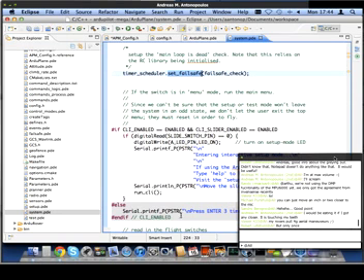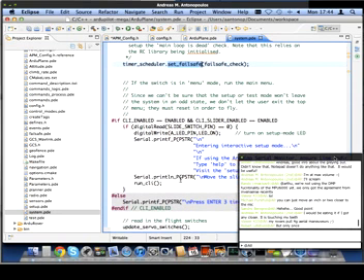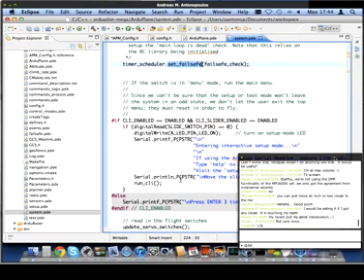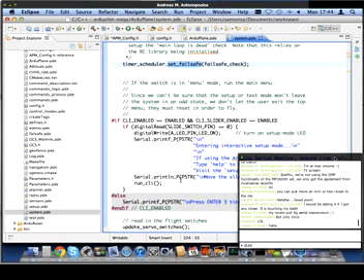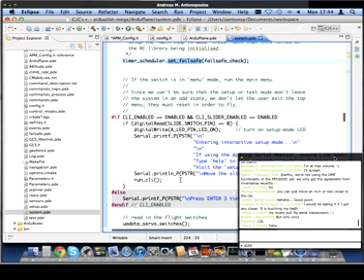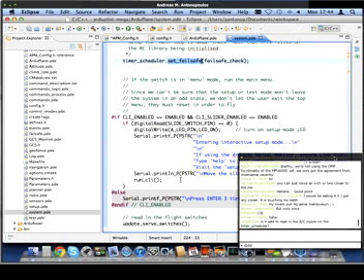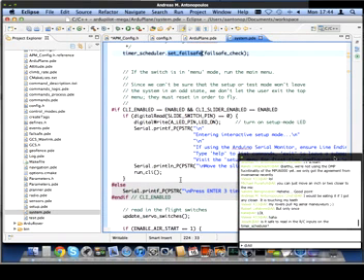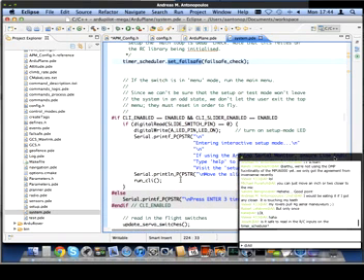It also provides the heartbeat behind things like the analog to digital converter, reading the gyros, reading the accelerometers, reading the MPU 6000, etc. So that's an absolutely central part of the way we run the APM2 at the moment. Basically, things happen at most at 1 kilohertz, so we never read data from hardware more than 1 kilohertz, but often quite a lot less.